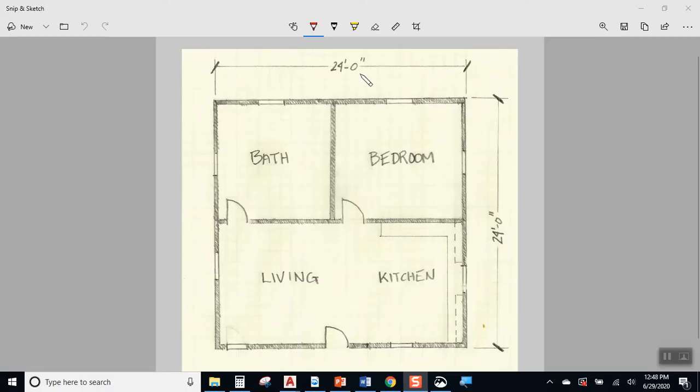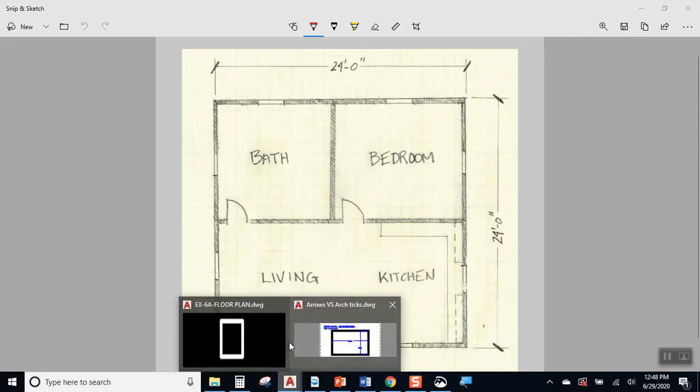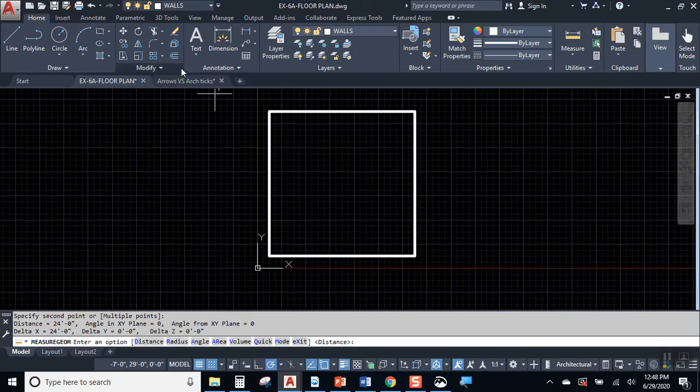Okay, so let's proceed. We see that on an architectural drawing or construction documents that walls are not a single line. Walls actually have some thickness. It's a double line, and sometimes it's filled in like this with poche. But for us, we can just draw 2 lines to represent a wall. So what we'll do is we will go back to our drawing, go to our offset tool, and we will set the distance for 6.